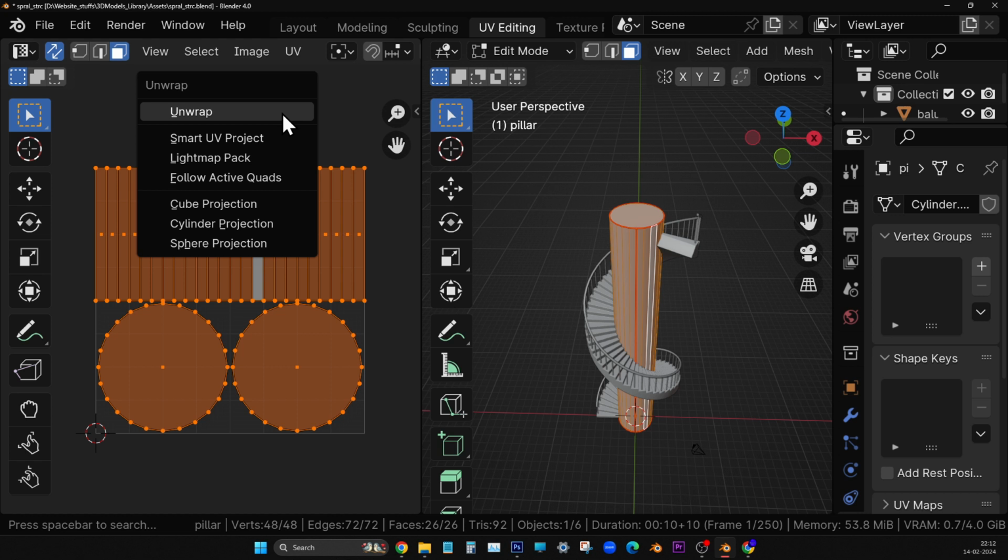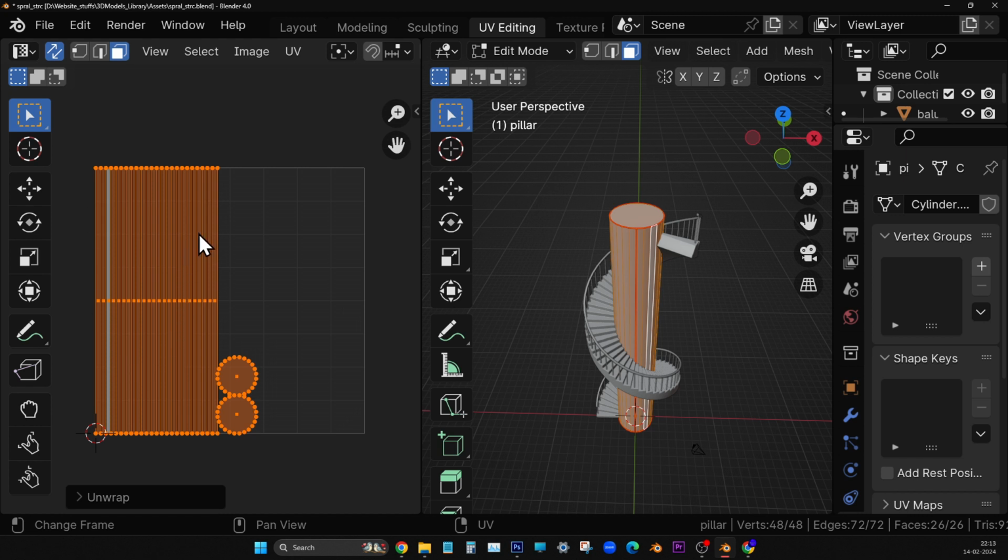When you are creating any sphere, cylinder, or cube, it will come along with some UV unwrap pattern. But this pattern we don't want because we have changed its dimensions. The height is more, all that has changed. So we did all transforms and marked the seams. Now we are applying unwrap. You see, these are the actual dimensions. The height has increased, no?